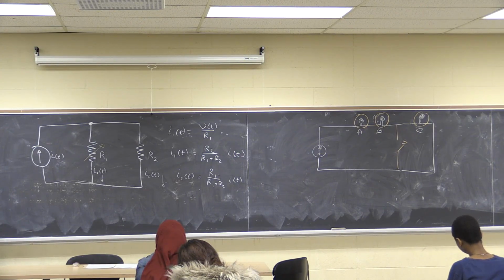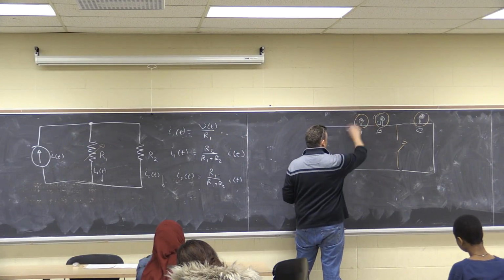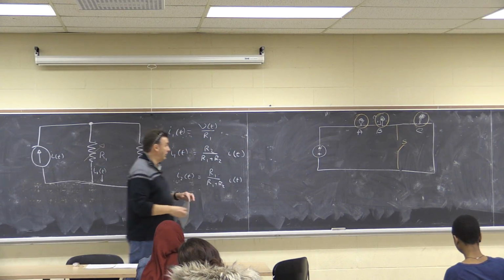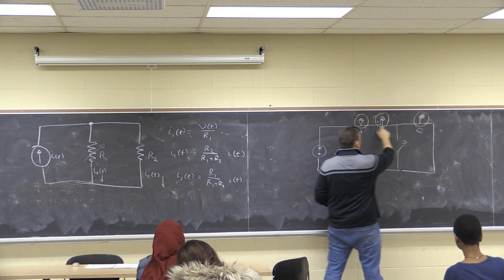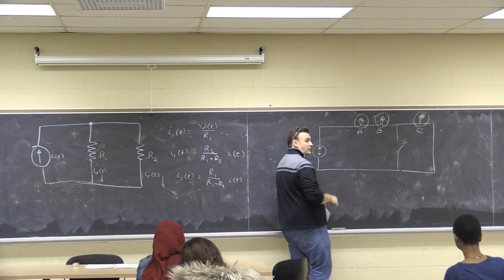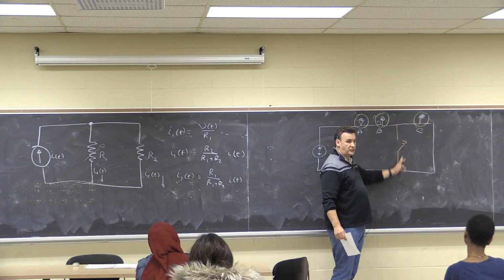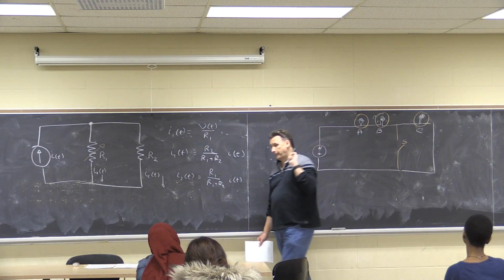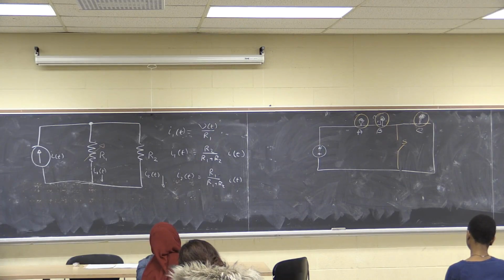Okay, so I close the switch, C turns off. You happy with that? I'm making a short circuit, so this is essentially resistors. So the lamp is a resistor, so it's high resistance, so it heats up a lot and generates light, or it's an LED or something. So in the original circuit, I go through 3, and I'm going to have some current flowing around the circuit. Close the switch. Resistance of this line is 0. No current flows through here, so C turns off. So what about the intensity of A and B? Increases? Same.